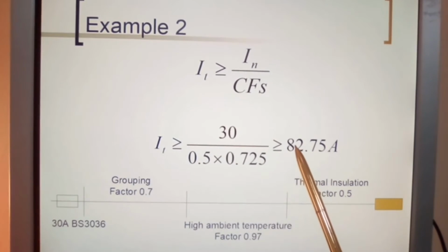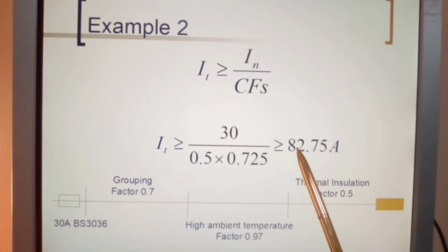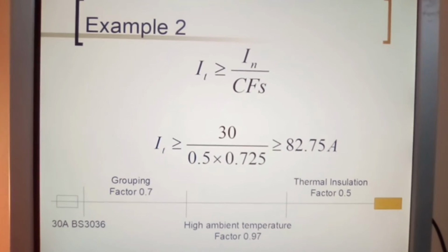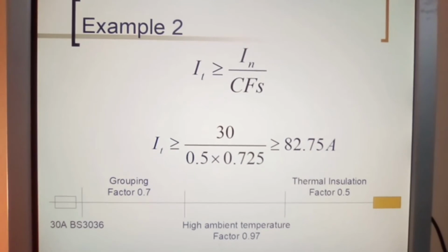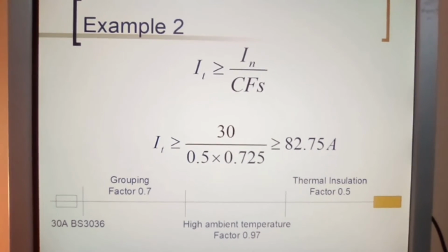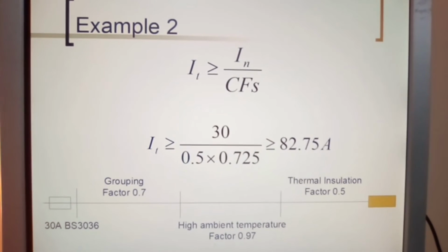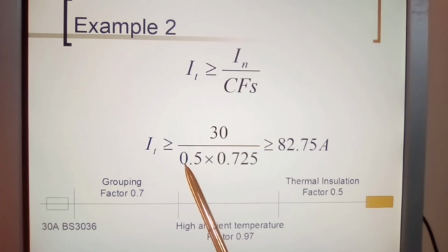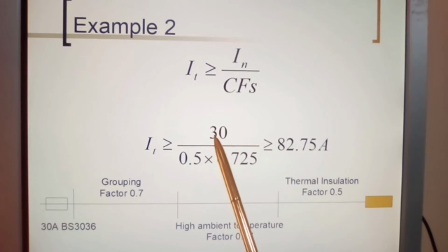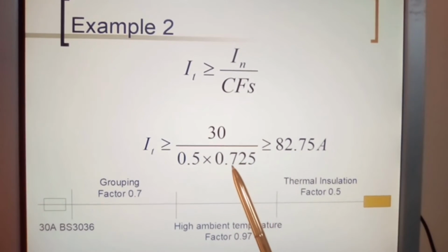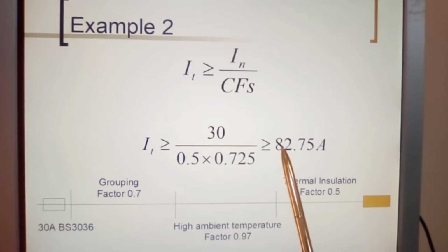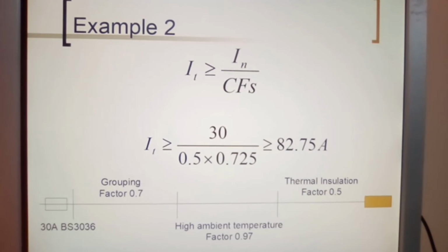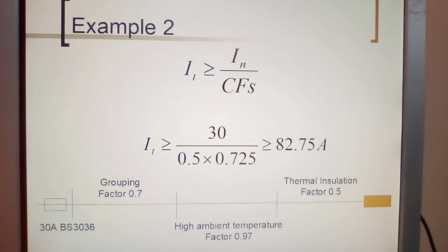You can see that here there's immediately an increase in the amperage, which means that the cable is going to be carrying a lot of current and getting very warm indeed. Remember you're dividing by the total factor, which should give you 82.75. Feel free to use your calculator to make sure you understand and arrive at that.